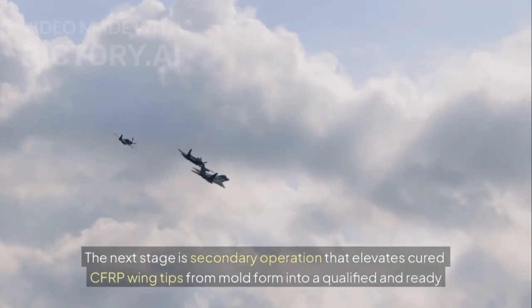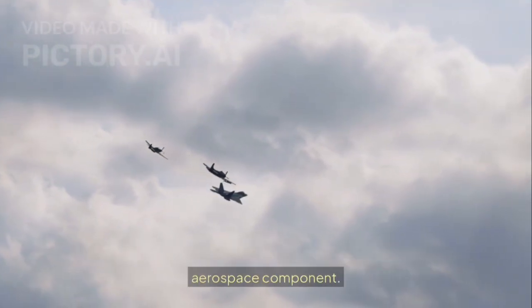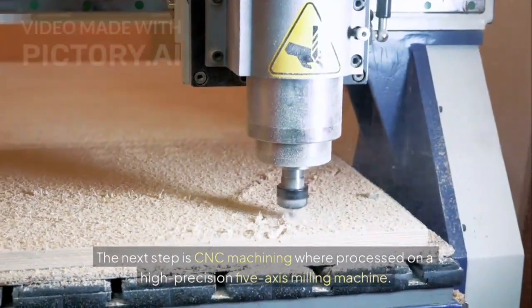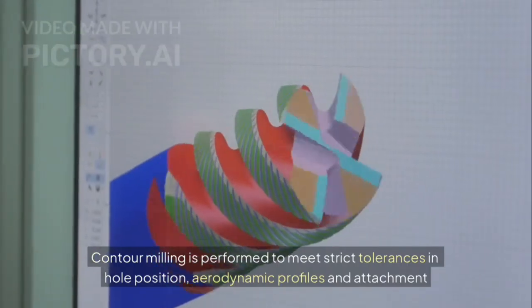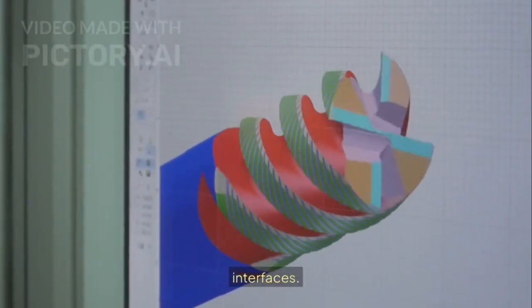The next stage is secondary operation that elevates cured CFRP wingtips from mold form into a qualified and ready aerospace component. The next step is CNC machining, where the part is processed on a high-precision 5-axis milling machine. Contour milling is performed to meet strict tolerances in hole position, aerodynamic profiles and attachment interfaces.